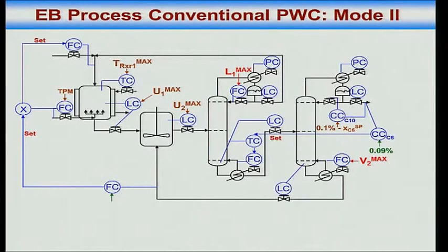Yes or no? Okay. So that increase in boil up is telling me what? That I am producing more ethyl benzene than I can boil off in the product column, and it is essentially building up in the 2 recycle loops. Alright. So how do I prevent that? Well, I use a boil up controller that does this. Does that make sense or no? I use a boil up controller that does this. Okay.